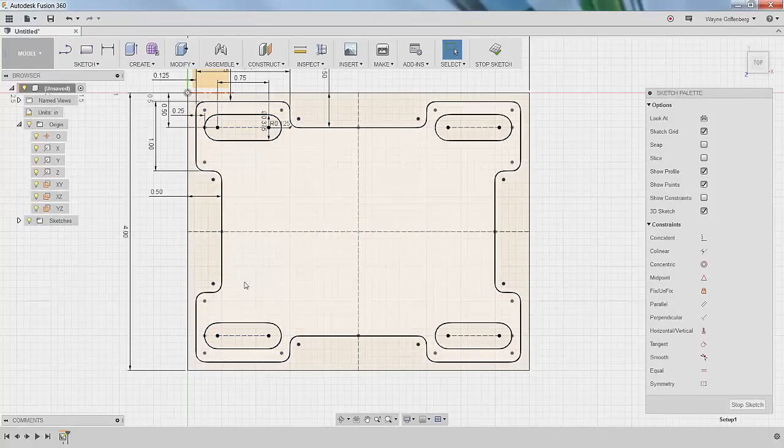And now if I hover over, you see the different regions we have. It's closed. It's a different region to work with. So as we start to build our model, we can choose these different regions to cut away and add and grow and so forth. So now I'm going to add one more feature. It's going to be that body above where the throttle body would be, down to the venturi of the intake manifold. So I'm going to draw that in.